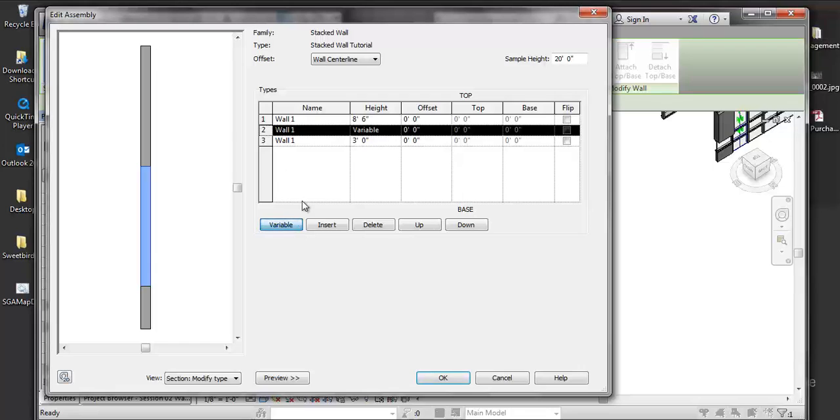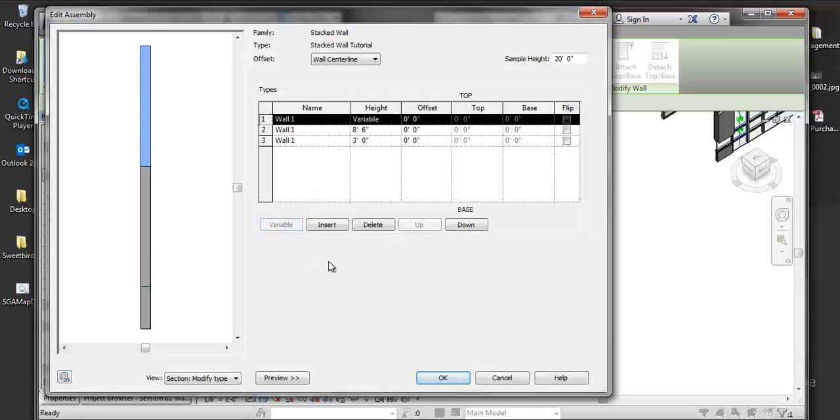What if there's like 2 places where the wall needs to be variable? Yeah. Don't do that. No. You put a stack wall on top of a stack wall. You could do that, yeah, you could do that. I rarely see stacked walls used anyway. It's only going to be when you look at your suburban bank, or whatever, or your grocery store, it's got the nice little trim at the bottom, right, for the brick.